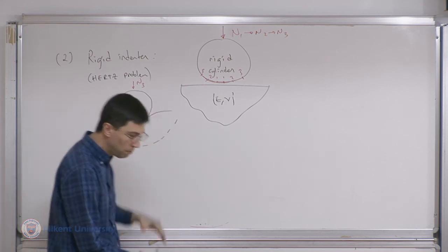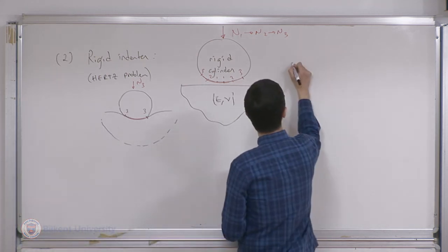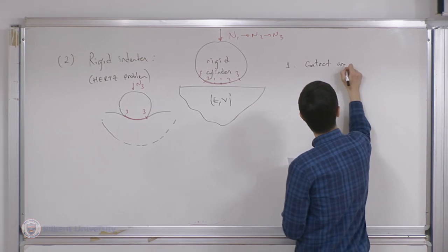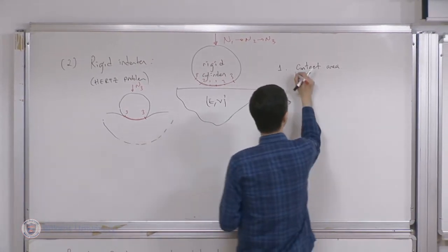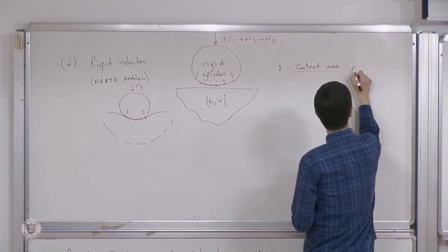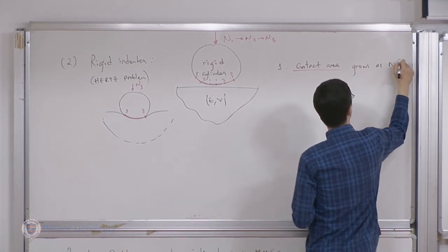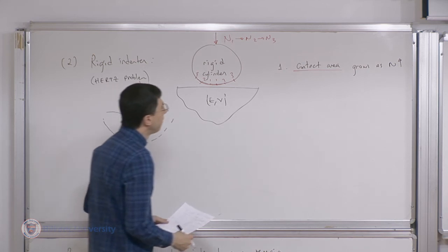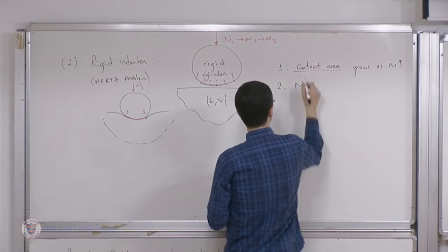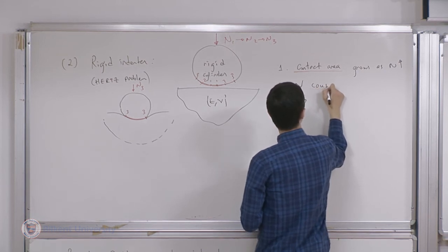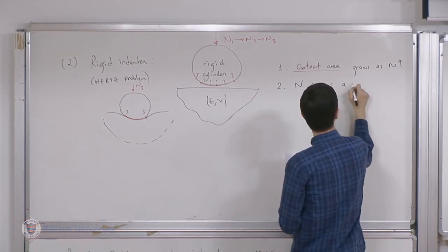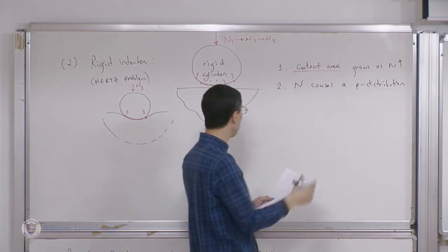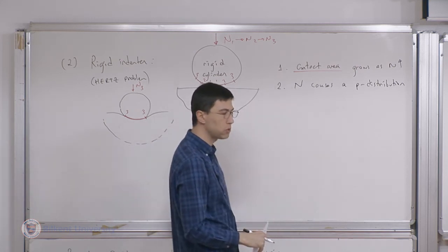So now let me sort of summarize the observations that one needs to follow in order to solve this problem. So first of all, I observed that we have an area that is associated with contact, and this contact area is not known beforehand. It grows and grows. Okay. The second one, the observation that I have already stated, is that due to the force, we have a pressure distribution, and the pressure distribution that acts on the deformable object is statically equivalent to the force that I'm applying.